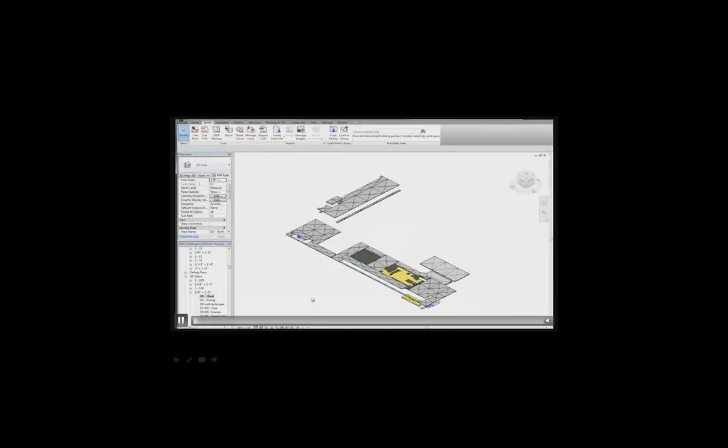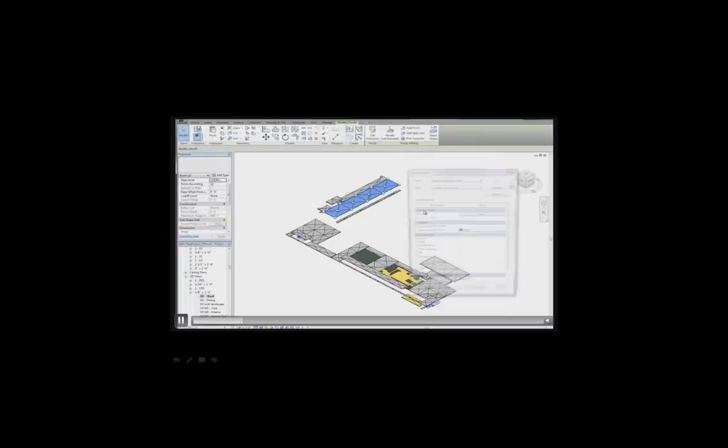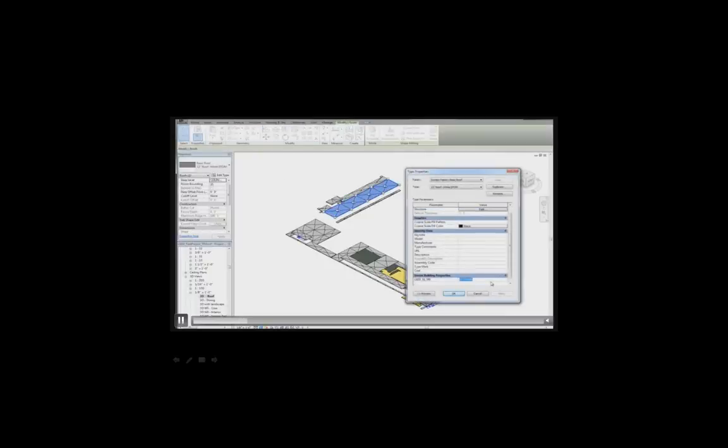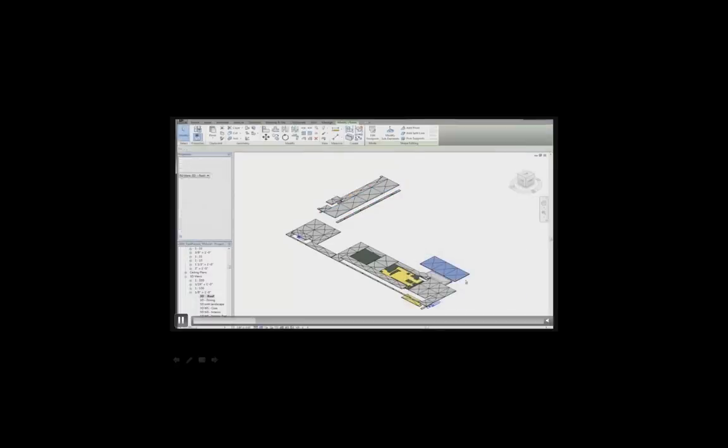So what you're going to want to do in your Revit model is you want to create 3D views that show only the roofs on the project. I'm going to have to look over here kind of to talk to you guys. So in the instance properties, you'll select the roof, and in the instance properties, you're going to indicate whether or not the roof is steep, right? This is a yes-no parameter that goes back to that 2/12 rule. So in our case, in this example, all the roofs are pretty much a low-slope roof, so none of the roofs are going to be marked as steep. And then in the type properties for each of the roof, you're going to type in the SRI value. Again, that's given to you by the manufacturer, and it's based on the total roof assembly.